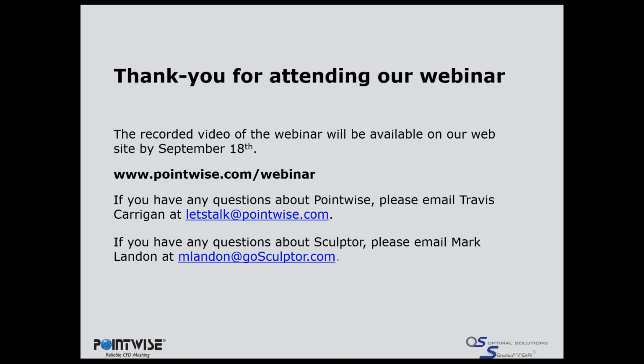Okay, do the viscous layers and volume mesh get recreated automatically, or do they need to be done manually? I'm assuming maybe recombined. The viscous layers on export will get combined into, if you're growing off of quads, unstructured hexahedra wherever possible. And if you're using T-Rex to grow off of triangles, they'll get combined into prism elements. And elsewhere are going to be tetrahedra or pyramids to help transition from quad faces to the tetrahedra, and that's all done on export.